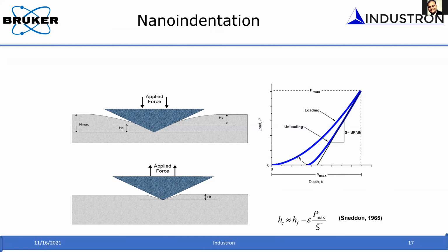Metals are basically incompressible. So where does that material flow? Sometimes the material may flow up to the surface, forming a pileup. And sometimes, when the material is annealed, for example, with a very low dislocation density, that volume displacement will be accommodated within the material, in which case you will get sinking.